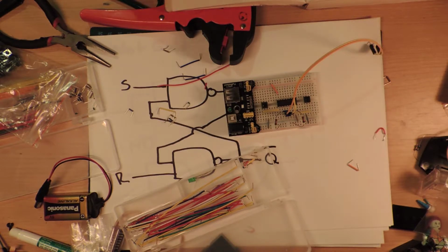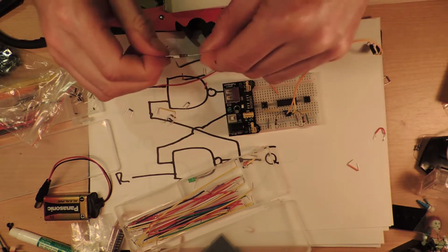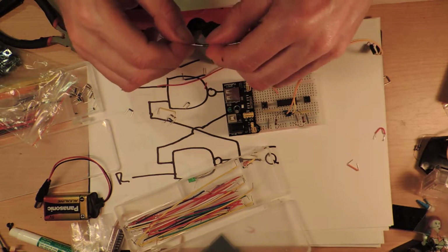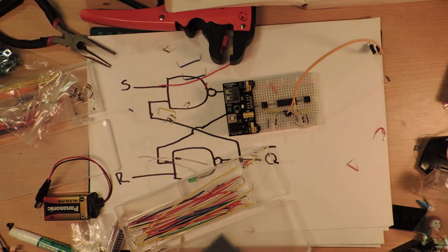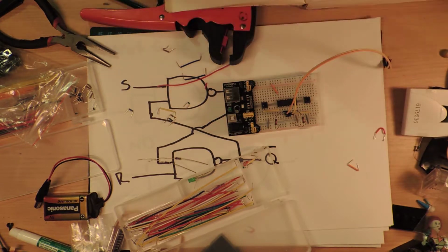And I'm going to use my trusty 470 ohm ones. So I was going to try and start using 1000 ohm ones, 1 kilo ohm, because you really are stressing the poor little things. They're not supposed to provide that much current. And these little LEDs, they light up just fine no matter what you do with them.